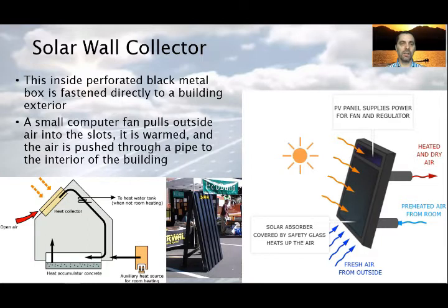During the day, the thermal mass absorbs the heat provided by the solar air heating system. At night, the thermal mass will slowly radiate the heat it collected into the living space. The more thermal mass, the longer the home will stay warm after the sun sets.